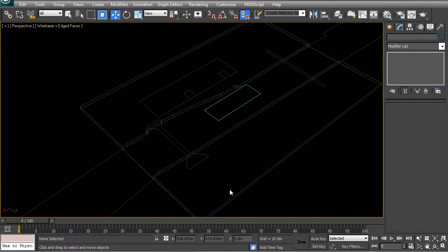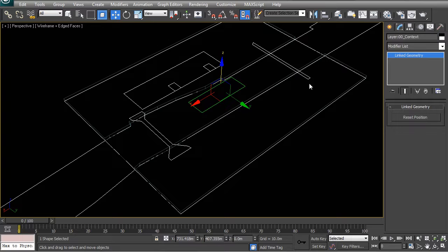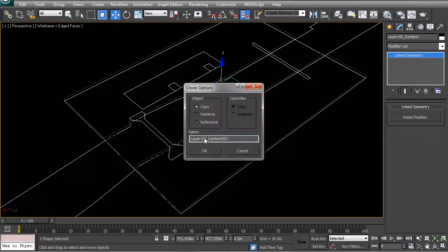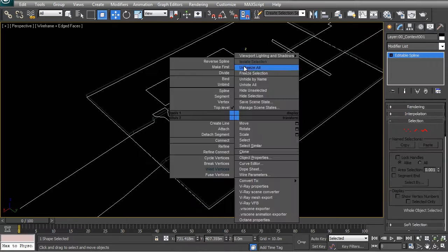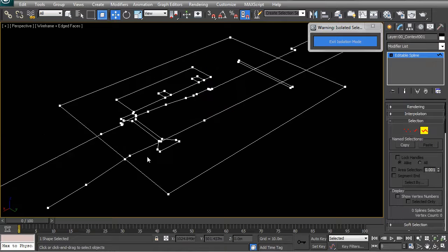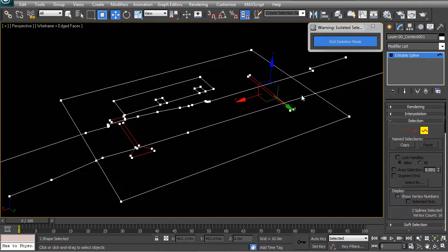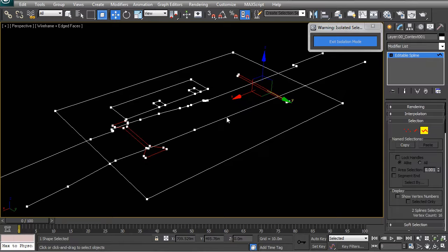So next I'm going to be creating these bridges, and in this case we can actually go and choose to copy the entire layer. So let's type Control V to that linked geometry layer. And if you remember from earlier on in this course, we discussed that if you want to use geometry from CAD that has been linked, you just copy it and you can then go and manipulate a copy of it and use it in your 3D Max file.